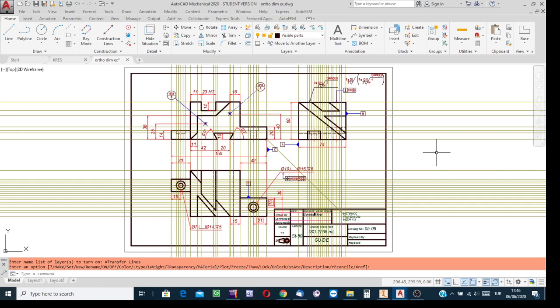Starting from the alphabet of the language, there are learning stages on the alphabet. In engineering drawing, saying alphabet, we mean different line types. Thick line, what is the meaning? Thin line, what is the meaning? Long dash, short dash, what is the meaning? Extension line, dimension line, visible outline, hidden line, cross-hatching line, transfer line, construction line. Using those lines, while we construct, we have the projections.